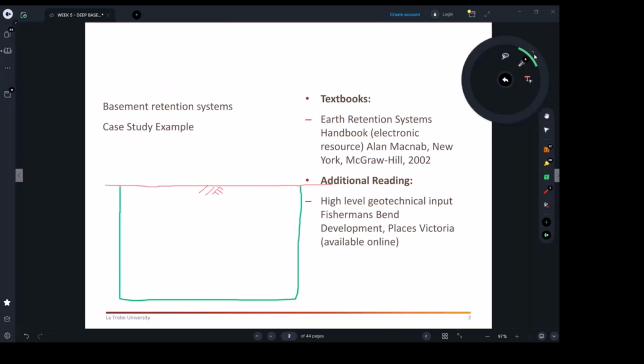Yes, the groundwater table. Usually in Melbourne, especially the south eastern suburbs, the ground level is lower, I think the lowest areas are around southeast Melbourne, close to the CBD. And usually you get seasons where the water table rises. You actually have water underground, a water table, as they call it. The water rises in some of the seasons, especially in a wet season. And if you are constructing during such a season, then there's going to be trouble.